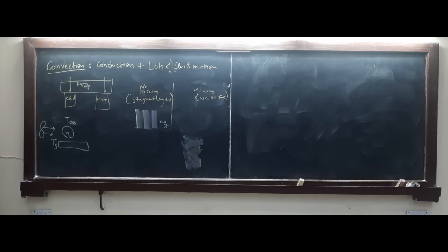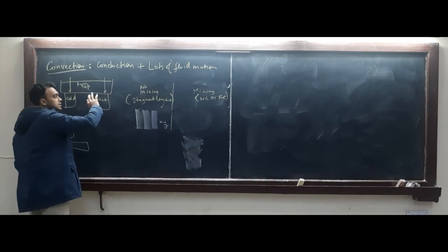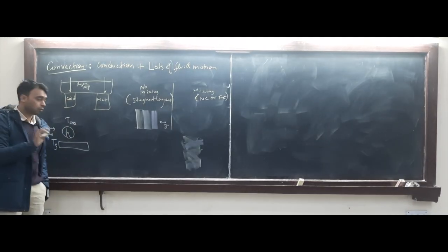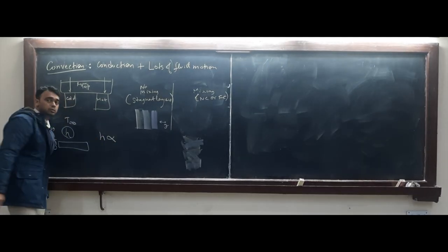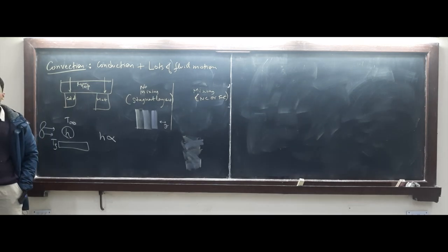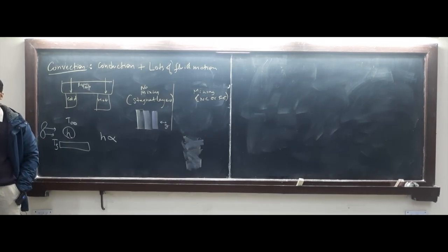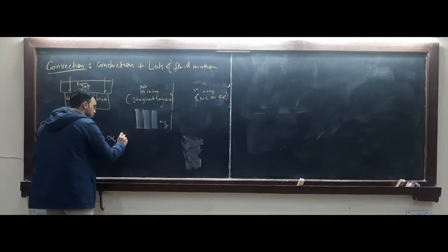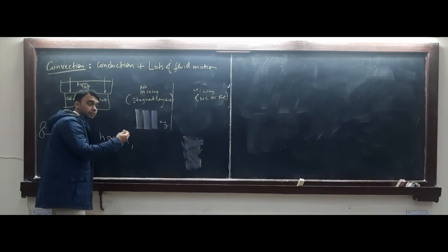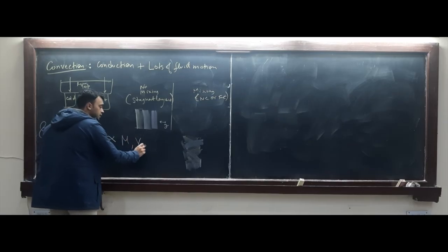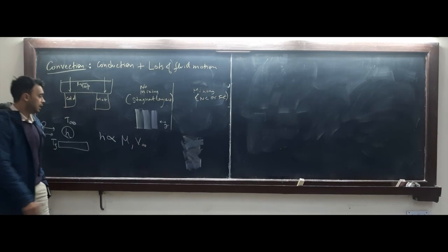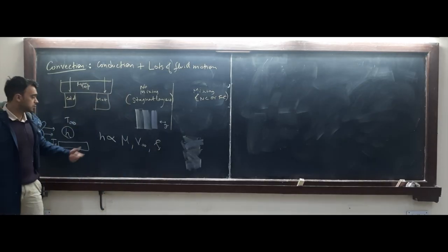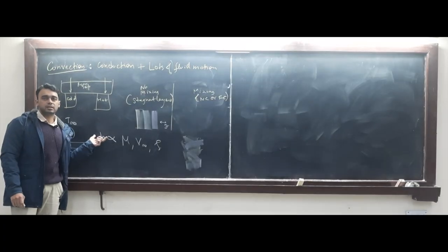Now, you can naturally imagine, since fluid motion is involved, the heat transfer coefficient h should be proportional to the viscosity of the fluid, the free stream velocity, how much motion we are generating, and density also sometimes, and all the fluid properties. So it becomes much more complex than the conductivity aspect.